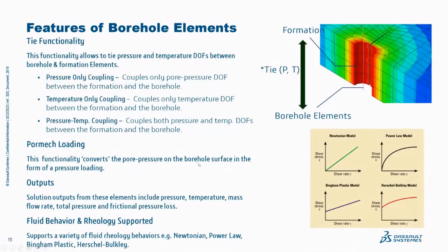These elements also allow us to model different kinds of ties between the borehole element and the reservoir rock. You can couple the temperature and pressure inside these borehole elements with the outside reservoir rock, and you have different types of coupling available. The coupling can be a pressure only coupling, in which case you only couple the pressure degree of freedom between the borehole element and the reservoir rock.